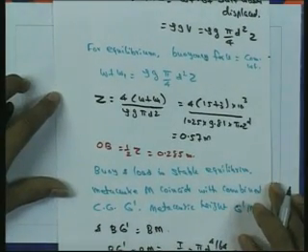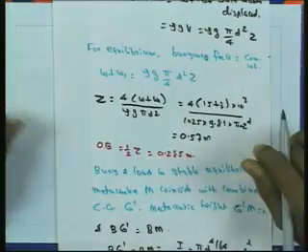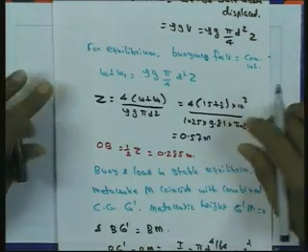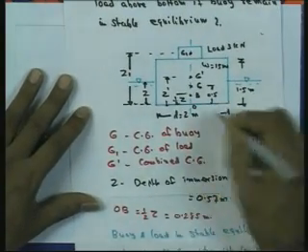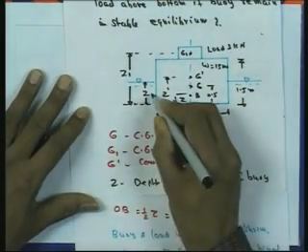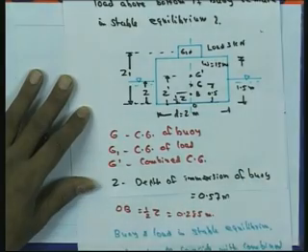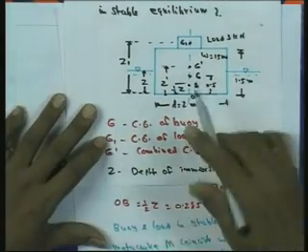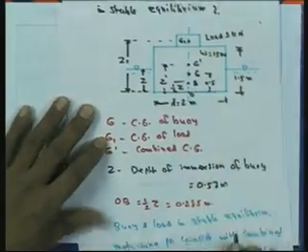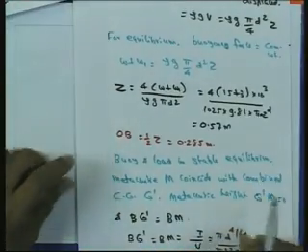Now we want to determine the center of buoyancy. In this figure you can see that this Z is already determined as 0.57 meter. So OB is equal to half of this Z. That is equal to 0.285 meter.